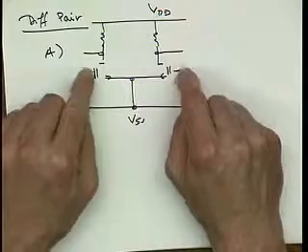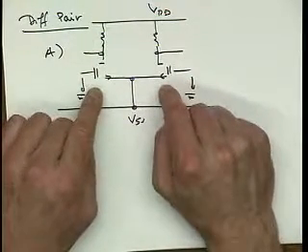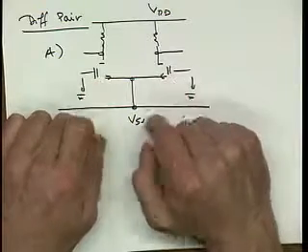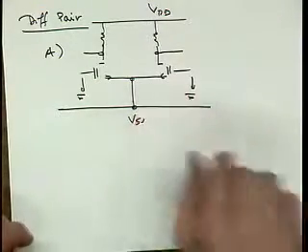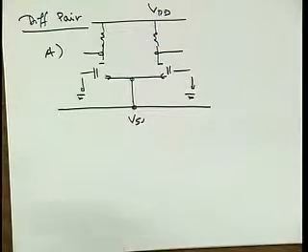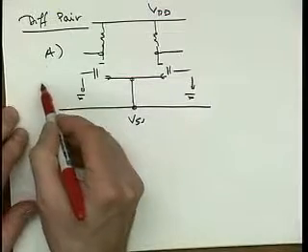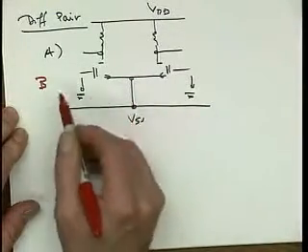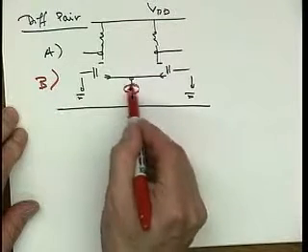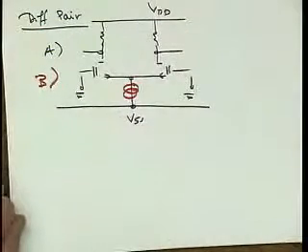Well, if I move these two terminals up and down, then the current flowing here is going to change, right? Because the VGS of these devices is going to change. So how could I make it so that this current doesn't change? Put resistance in here? Yeah, that would help, even more with a current source, right? So that's why we put this current source here.